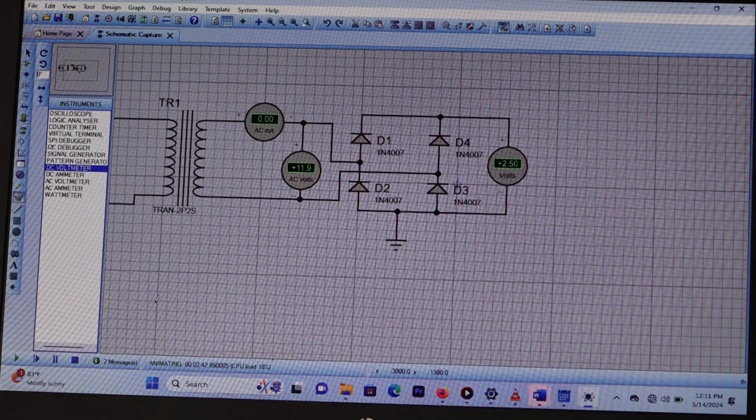So in order for current to flow through the diodes, the supply voltage should be greater than 1.4 volts to overcome the potential barrier of the 2 diodes that are in forward bias.